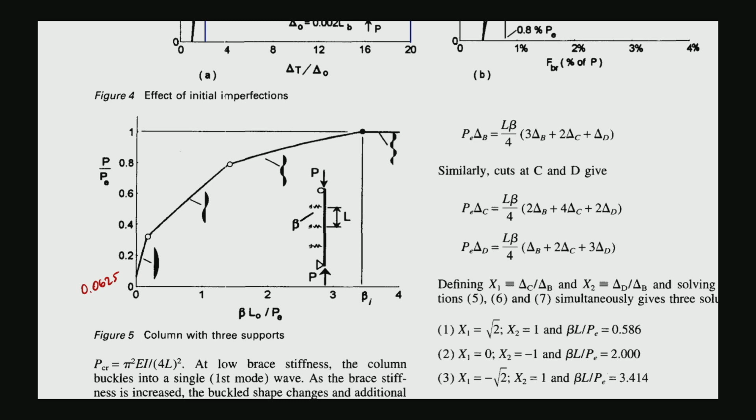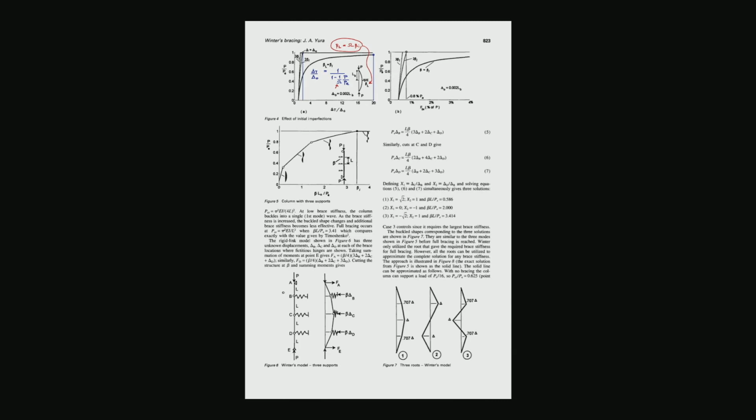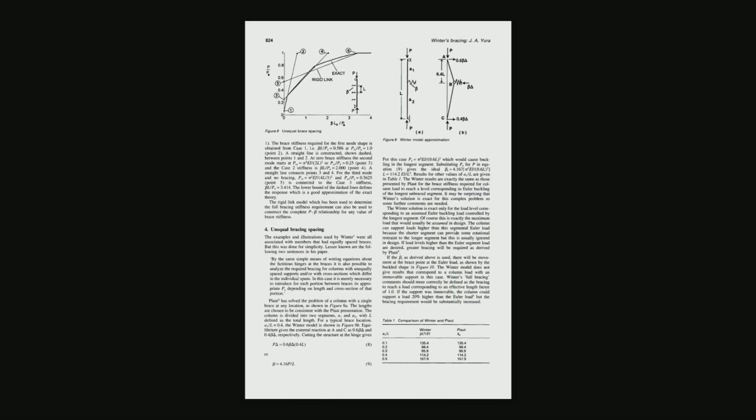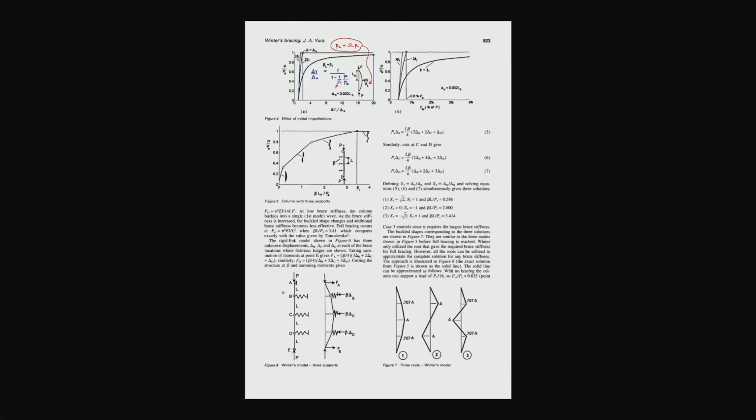And then you increase to some point, and the buckling is changed from half sine curve to 1 full sine curve like this at this value, and then you have this buckling shape until your stiffness approaches this new number, and then you can form this until the stiffness is big enough. Then you can form 2 sine curves. So this is interesting, but it is going to be laborious for the hand derivations. It is possible. It might be fun for you, but I think we might be able to do something fun using the buckling code that we prepared already.